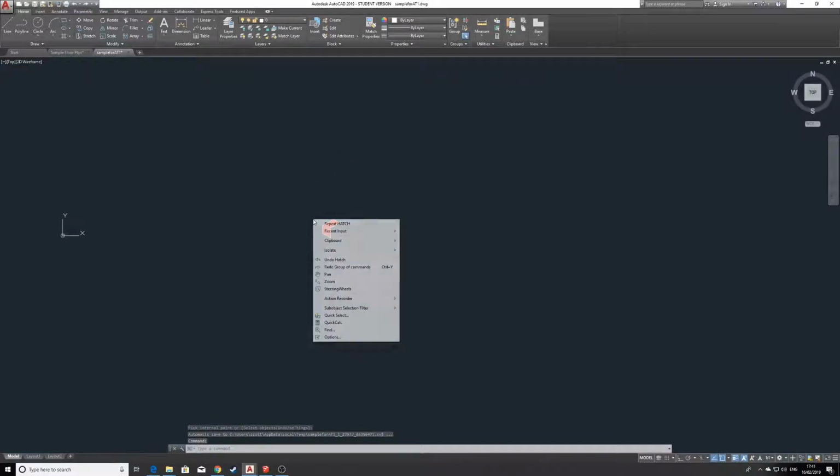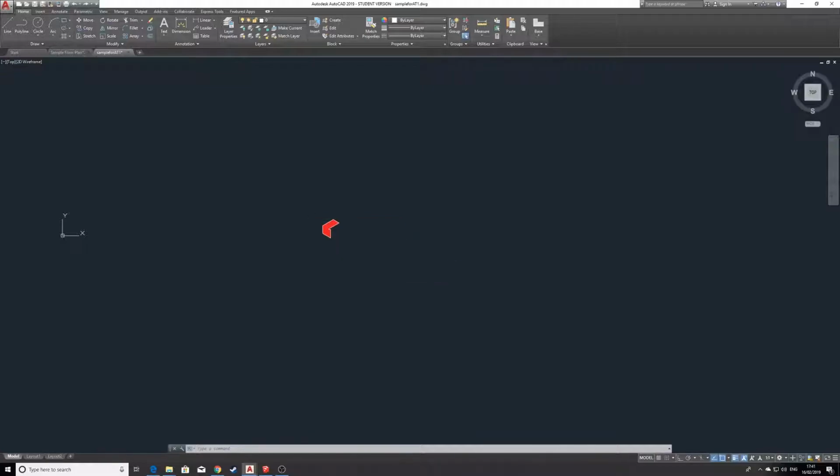So we've hatched that. We go right click, isolate, and end object isolation again. And then once we're back onto the main scene, which should load up in a second, we'll just draw this at the back of the stack again. So we'll go on the draw order and send to back, and then that'll be our second diagram done.